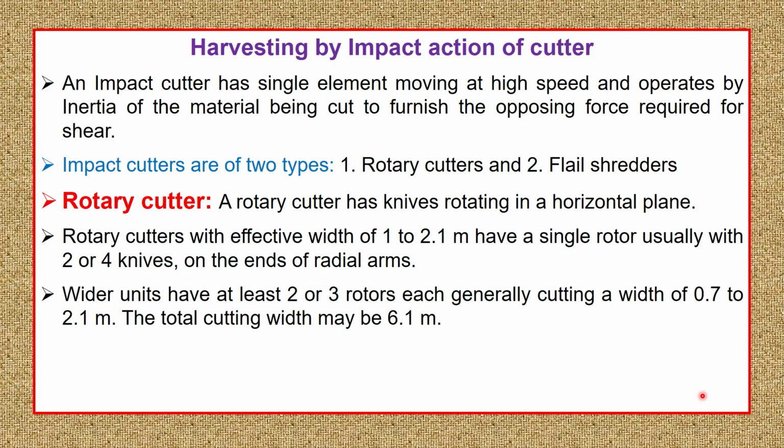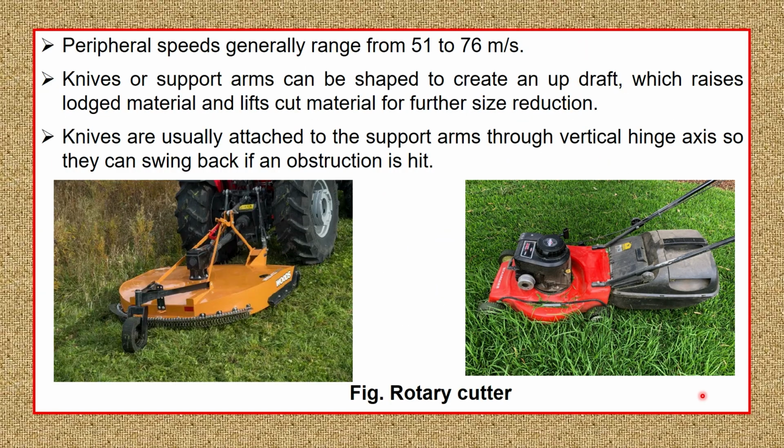Sometimes there will be two to three such rotors arranged side by side, so that the coverage width of the cutting area may be increased up to 6.1 meter, where each individual cutting rotor's cutting width will be around 2.1 meter. In such cases, depending upon the number of such units placed one beside the other, the working width will be increased.